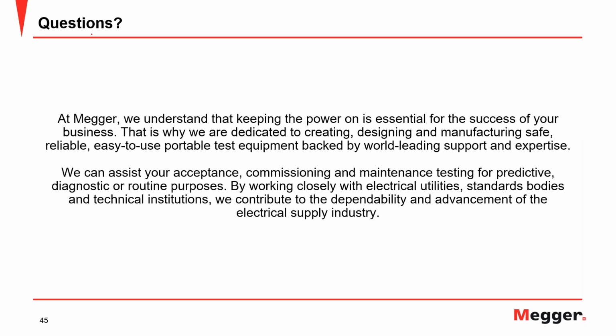And so that's not only influencing line frequency bushing test results, but other frequencies as well. So I'm talking things like salt contamination on a bushing, or carbon, or high humidity, which is another frustrating one. If you're over 70 to 80% humidity, that can certainly influence your results.